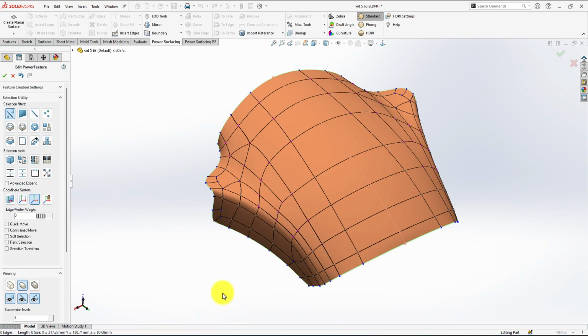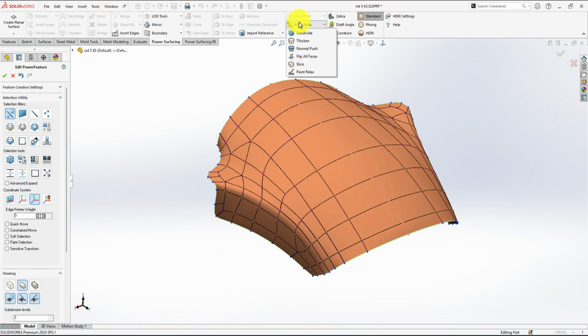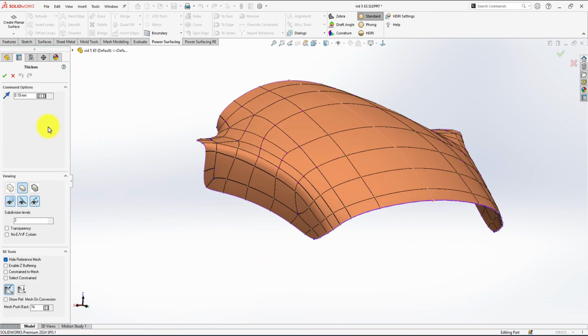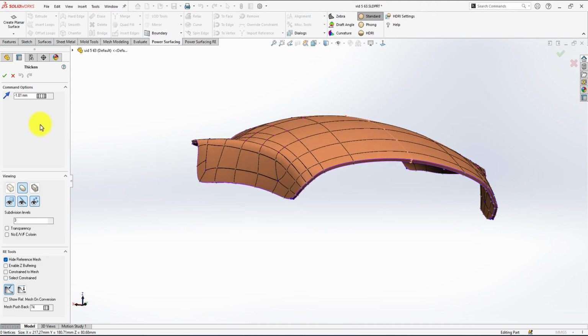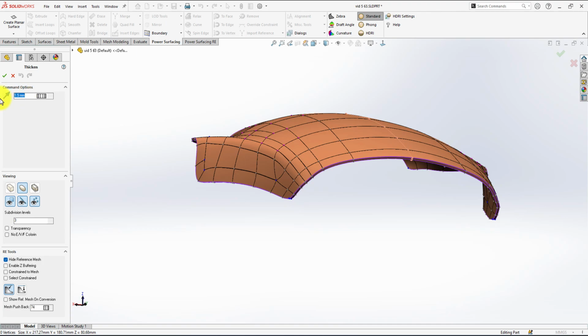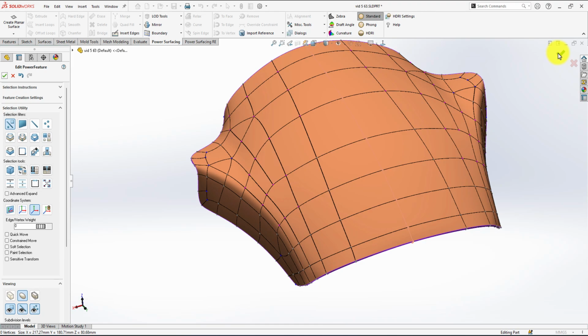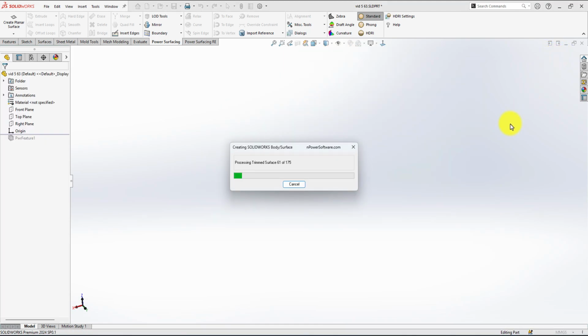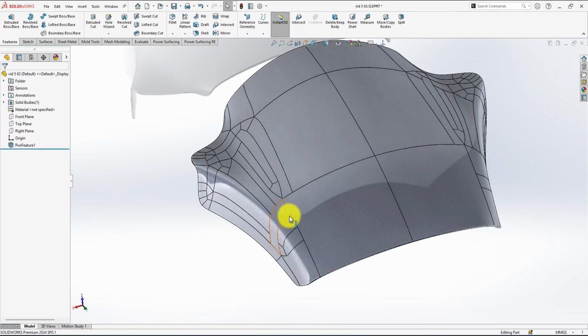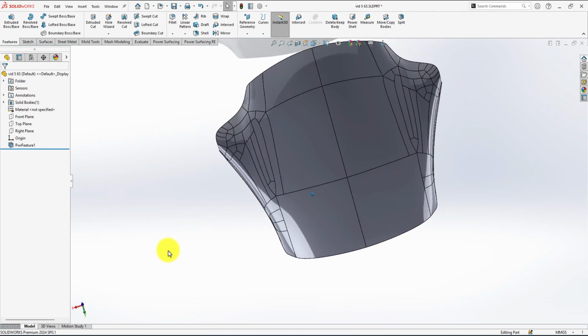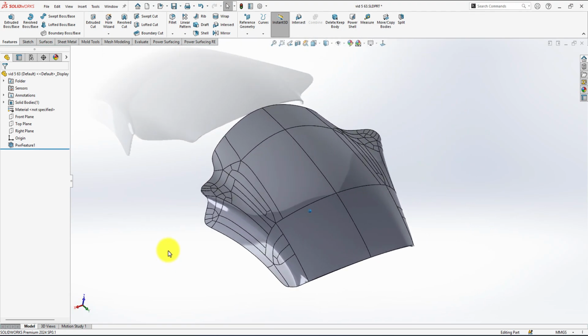now I believe I can make thickness to it. Here to the mesh tools, thickness, and with the minus, maybe 1 point, or maybe 1.5. Okay, it should be with the minus, and okay, convert. Okay, that's set. Here's my solid.